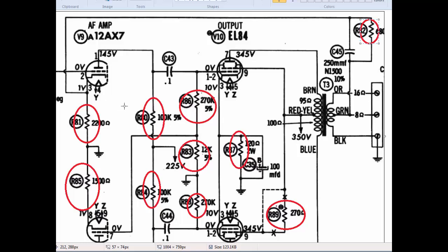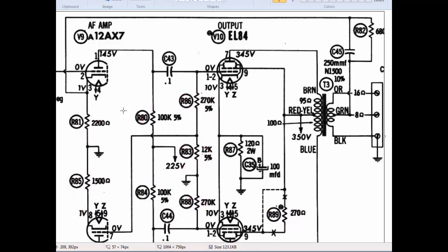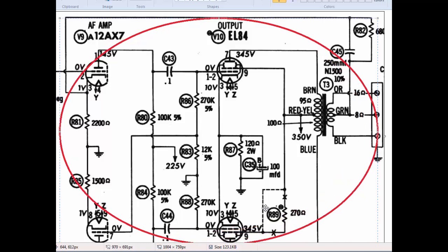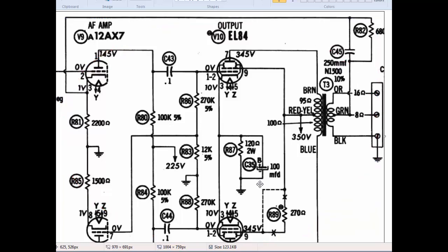It's to drop voltage from some given point to another point to get the voltages where you want them within the amplifier. So if you look at this whole schematic from one end to the other, heck, you've already figured out what probably 3/4 of the components in here are and what their purpose is in a tube amplifier and in the design.